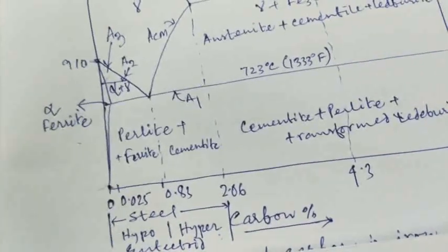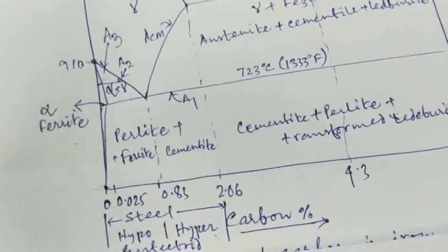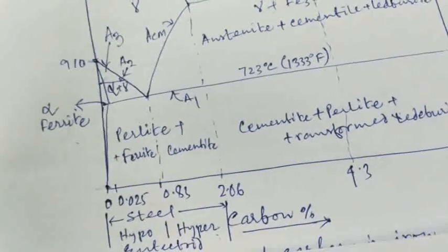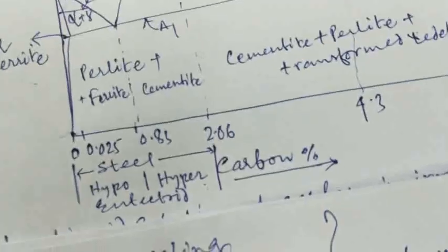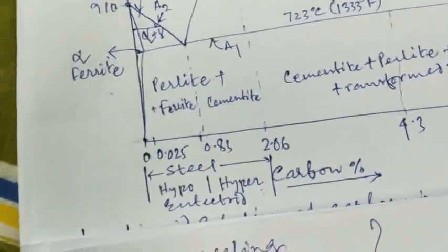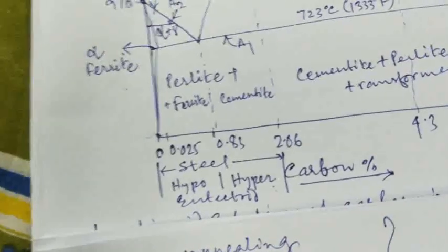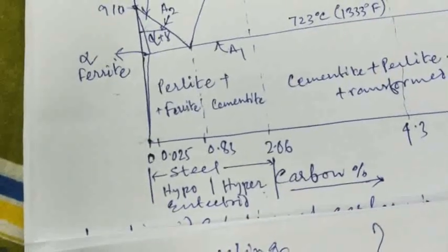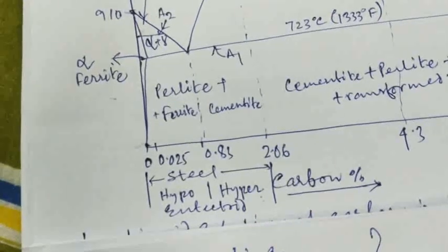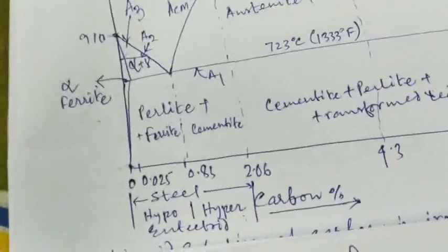Objectives are to refine grain, make the structure uniform, eliminate internal stresses, reduce hardness, and improve machining of steel. As we know, if we improve ductility in a material, it will increase the machinability of that material. In order to improve productivity in actual production, the parts are taken out from the furnace for air cooling when annealing cooling reaches about 500 degrees centigrade.